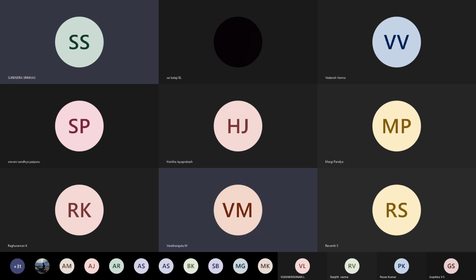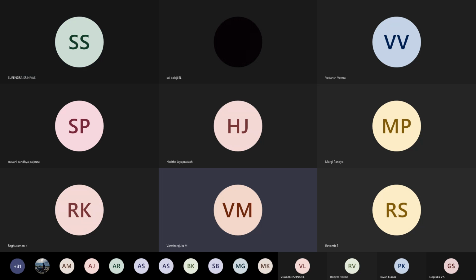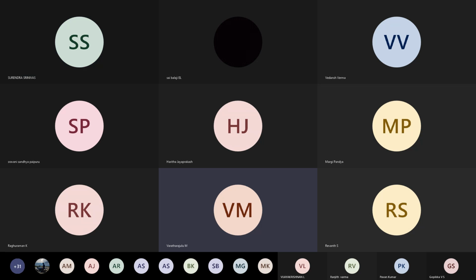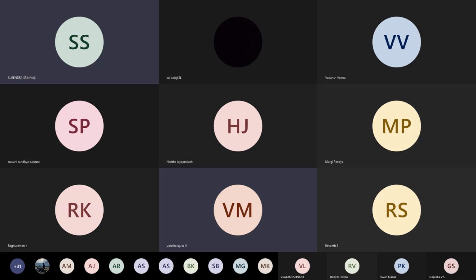During the upper part, we need to keep the runner and riser. In order to fill the molten material, we need some provisions. We need to pour using a provision called the runner, and we should have an idea whether it was filled or not, and based on the riser, the molten metal will rise. Therefore, that is usually called the riser. And once we have kept the upper cope in the upper part, filled it with the sand, and rammed, closely packing the molding sand, then what we need to do?